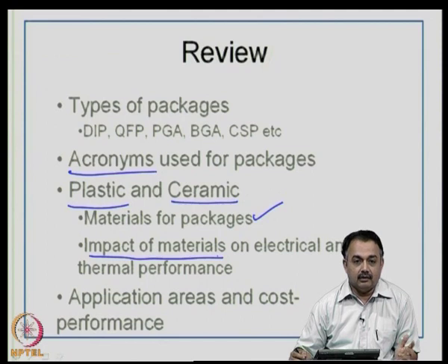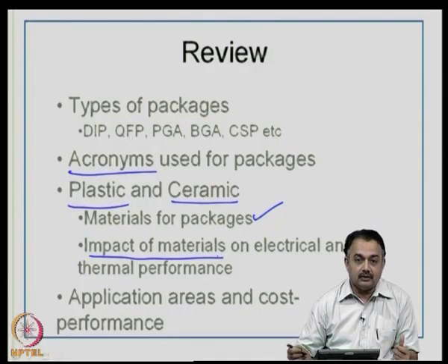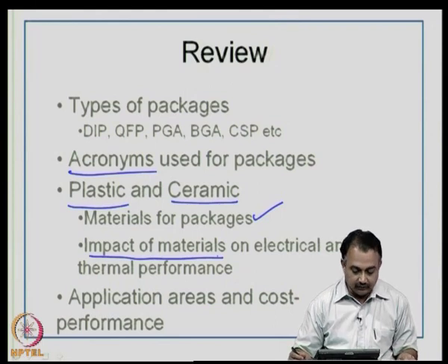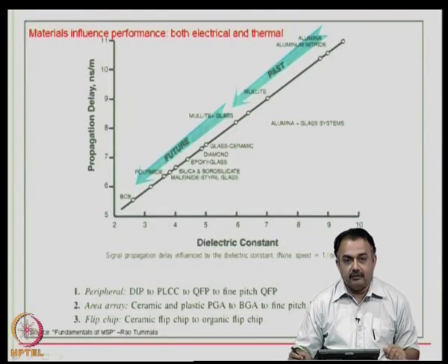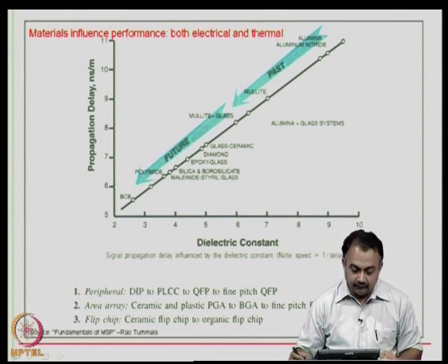It could be a microcontroller package in a QFP format, but in consumer electronics we could probably go with a plastic, whereas for an automobile application we could go in for a ceramic package. So, application area and cost versus performance are very key drivers for the package selection and also the package manufacturing. So, we will now go ahead with the other topics in packages.